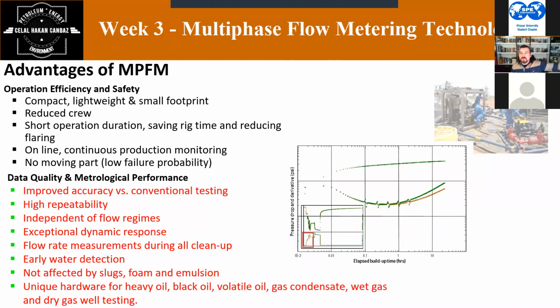Okay, your neighbor well can be different. Your well can produce different composition. This is possible. So each well, or maybe you are producing from multiple sections, right? You have different phase zones. You are producing from 3 different zones in one section. So it's a commingled flow you are producing, and the amounts and the compositions can be different.